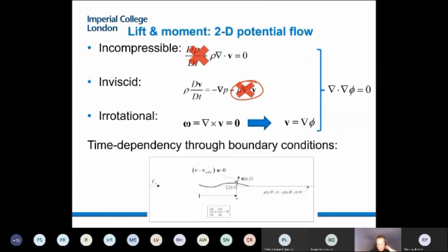So there is a third element to the problem, which is that this is on an airfoil, and what I put here is a cartoon of how the airfoil looks with arbitrary deformation. This line here, I refer to as a flying carpet. This is an airfoil which is deforming in an arbitrary way, and this psi is the local position of the airfoil as you move along this axis. So what you have in those cases is a flow which is driven by the potential flow equation, the Laplace's equation of the velocity field, or the velocity potential.